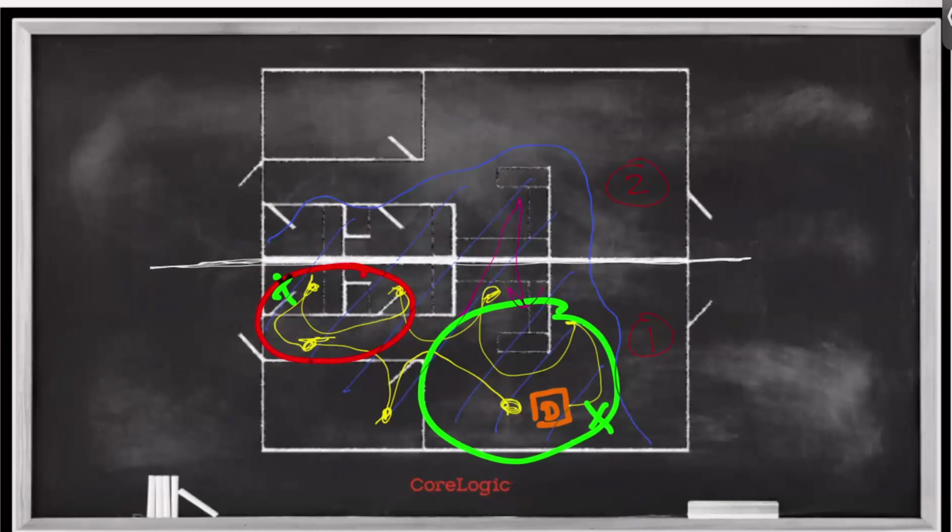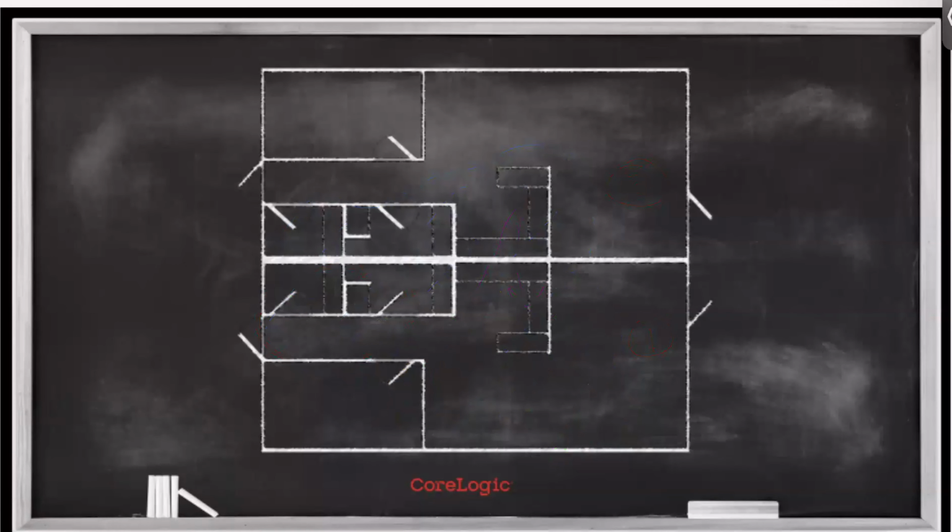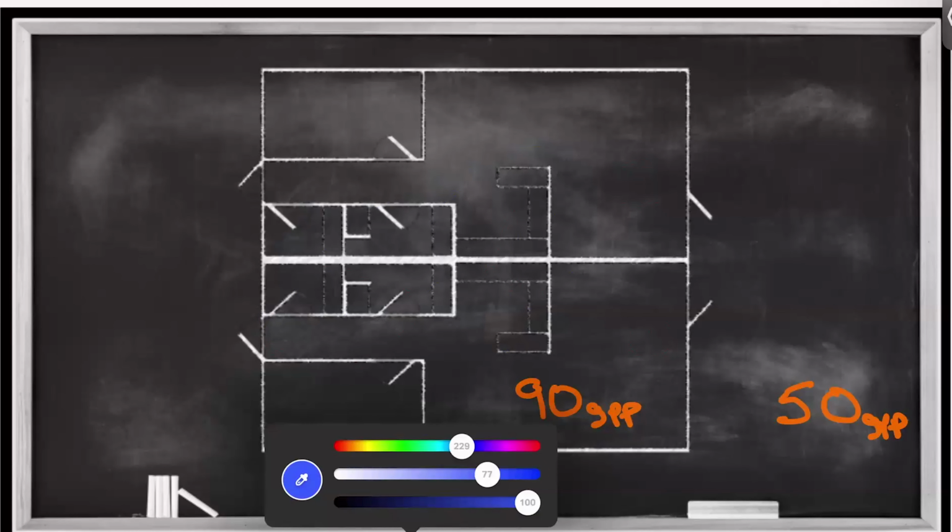If I go back to this analogy from the floor plan that we had earlier, let me clear this ink out of here real quick. Let's say that outside we have taken a temperature and humidity measurement and we find out that outside there are 50 grains per pound, and in our drying environment there are 90 grains per pound. And I decide, let's use some of that outdoor air to benefit our drying system.